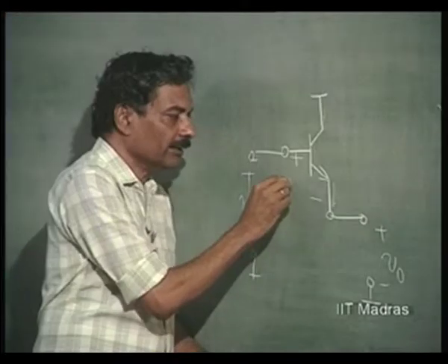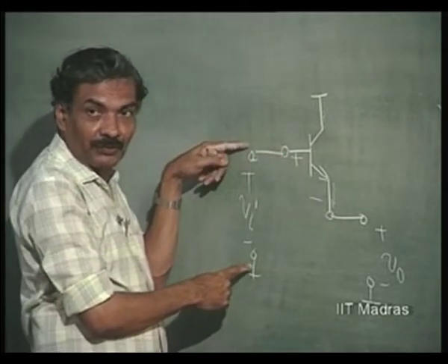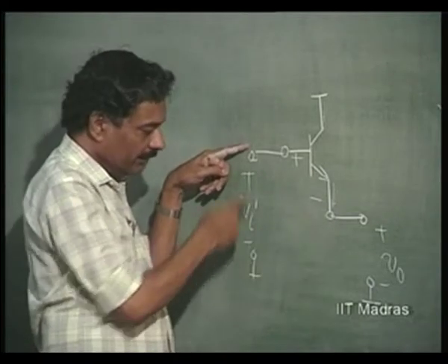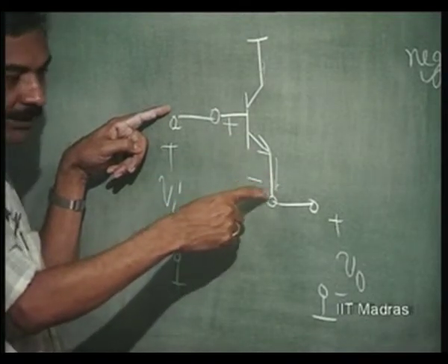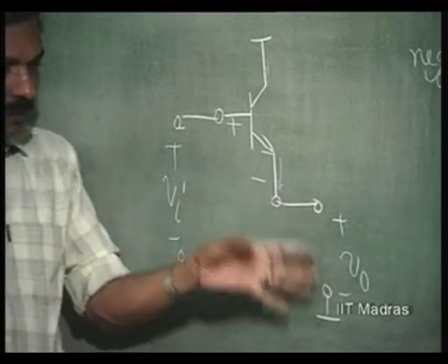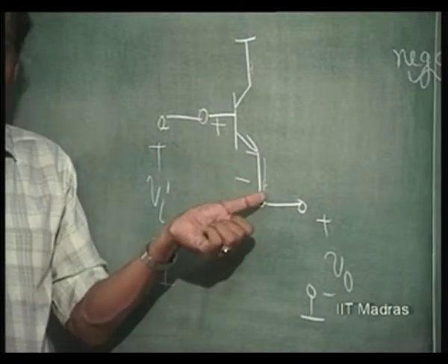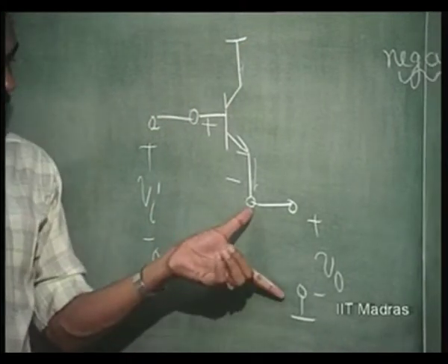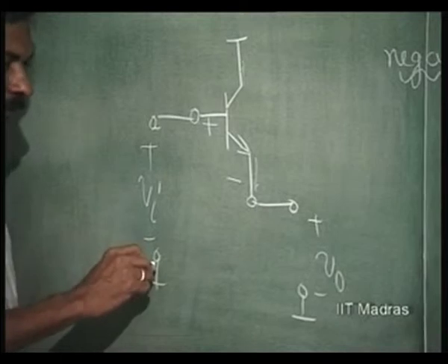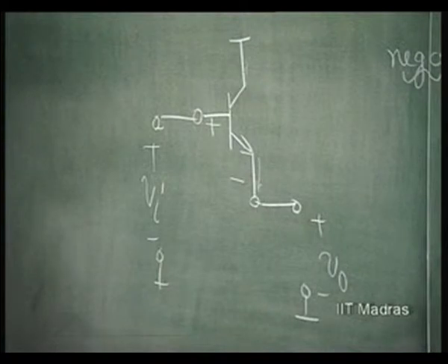This is the amplifier, input terminal. This is the actual input before feedback. This is grounded. So, this input was directly getting applied to base and emitter junction. Now, base emitter junction comes in series with the actual output voltage. So, I can take the output as well at this point because Gm times VBE is also available as current here. So, I connect this to ground and take the output voltage here. So, now this input voltage minus this output voltage is this input. So, this is exactly what we had considered earlier.